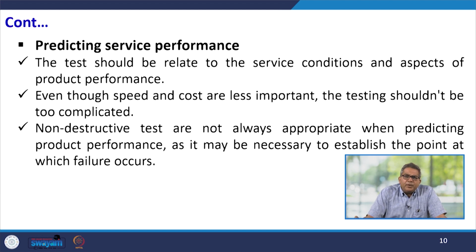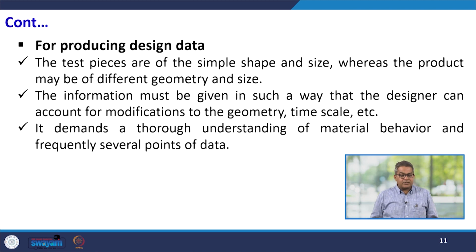Now, predicting service performance. The test should relate to the service condition and aspects of the product performance. It is quite obvious, because suppose I need to use this particular equipment in a humid environment, then it is quite obvious that the test should relate to this kind of service condition. Even though the speed and cost are less important, the testing shouldn't be too complicated. And NDTs or non-destructive tests are not always appropriate when predicting product performance, as it may be necessary to establish the point at which the failure occurs.